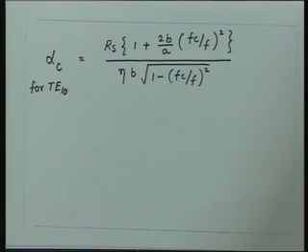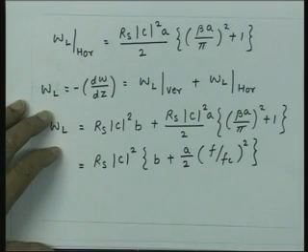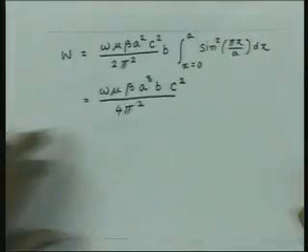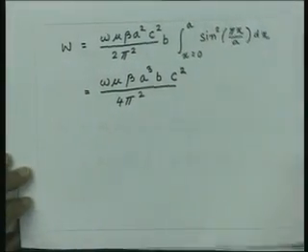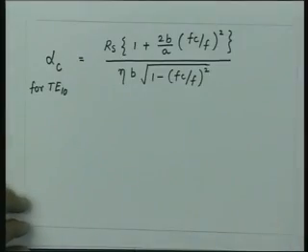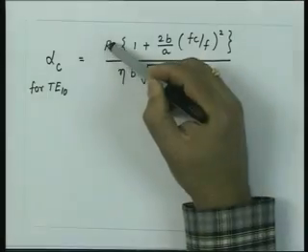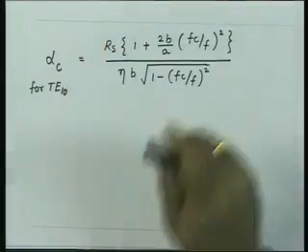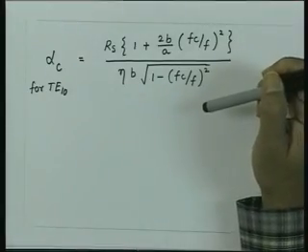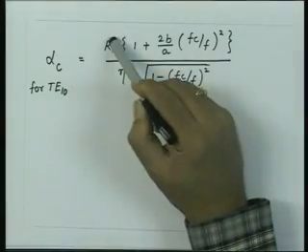It is a matter of only algebraic manipulation that from here WL and W which we have derived, we can write this quantity in terms of the cutoff frequencies and the frequency, and while doing little algebraic manipulation you can get the expression for the attenuation constant. Again, since RS is square root of omega mu divided by 2 sigma, the attenuation constant again increases with frequency.